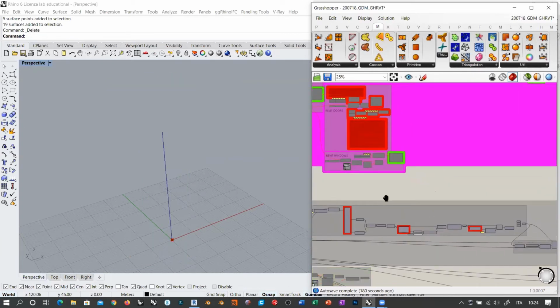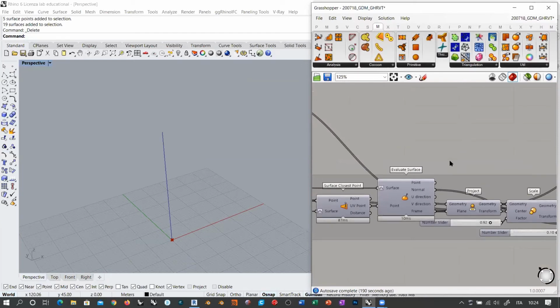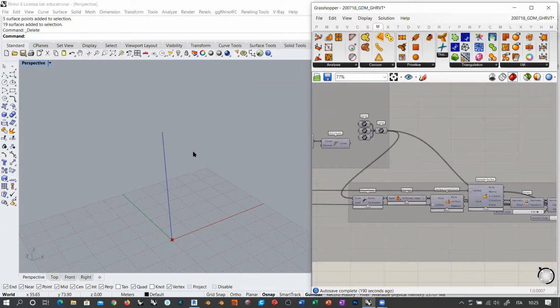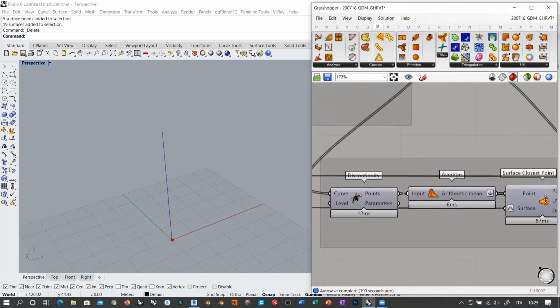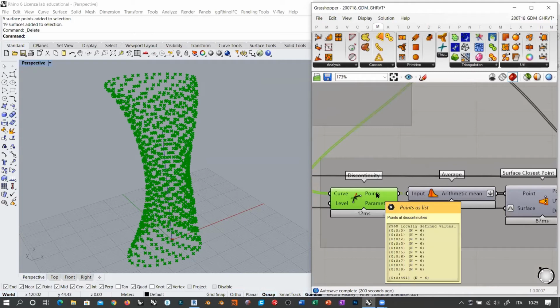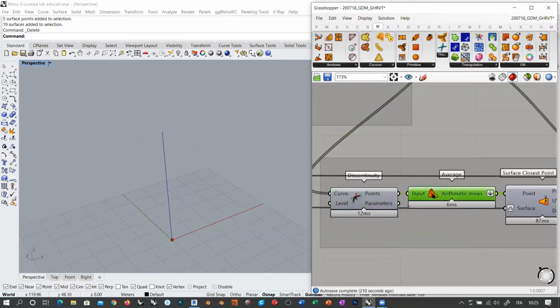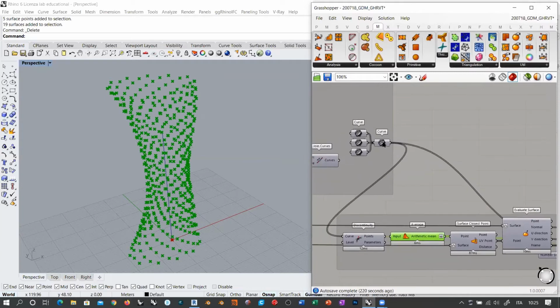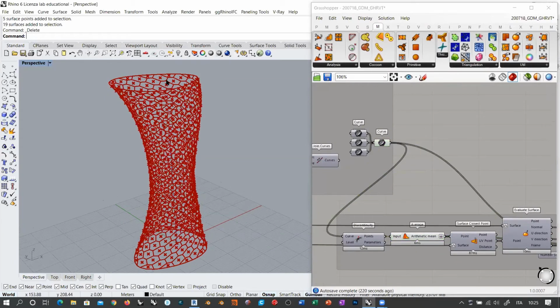you cannot work like this, because you cannot obtain a NURBS surface from a set of 6 points. So these are basically all the vertices of our hexagonal panels. You cannot create a surface from 6 vertices unless you want to use the patch command eventually. But I don't want to use a patch command because a patch is a trimmed surface once again, and we need an untrimmed surface here. So I took the average point. You see that the average point is more or less the centroid of this panel.